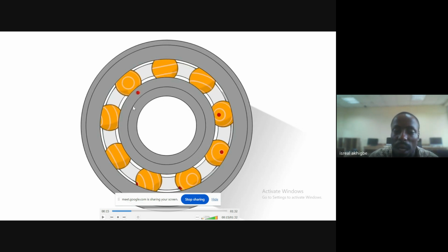If not, the intended purpose of bearing, which is to help us reduce frictional resistance, would be defeated; we would even be aiding frictional resistance. So to prevent that, manufacturers in the design of bearings have put in a separator, also called a cage. It separates them, like a kind of guard. It allows them to stay in the same position while there's relative rotation between the inner race and the outer race that is static. That way we reduce friction greatly.